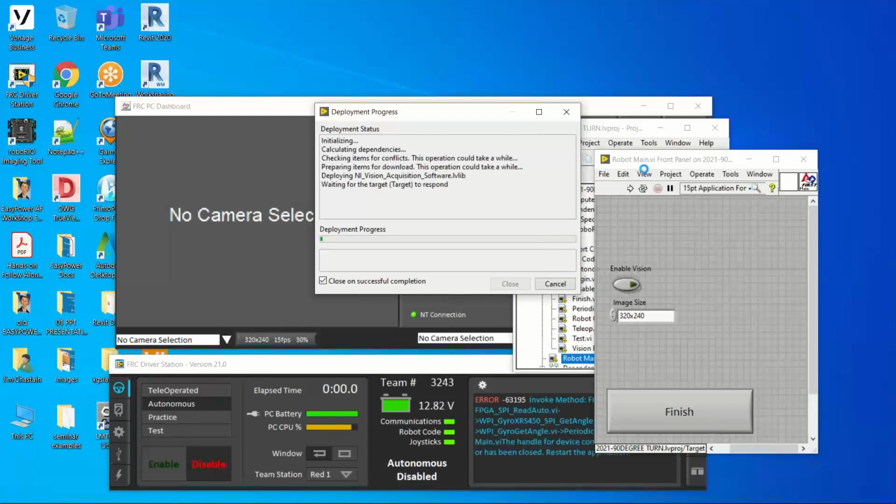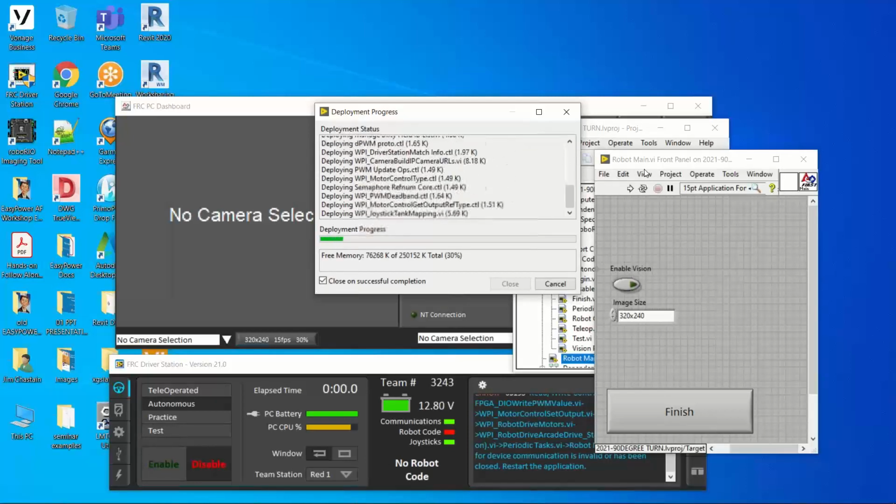I think, Charles, you were talking about compensating for inertia. You'll find that once you get into these 100 pound plus robots, you can just put braking on the motor controllers and they pretty much stop with not that much inertia. If you don't put braking on it, then it will glide a little bit.